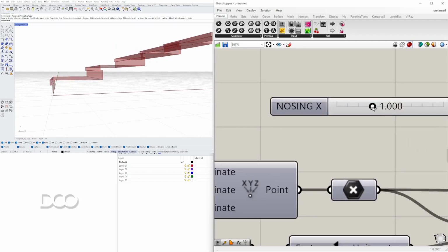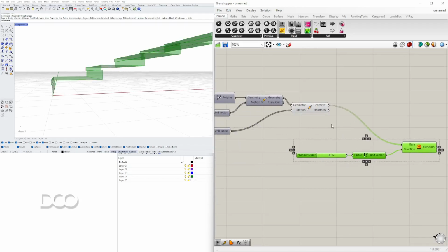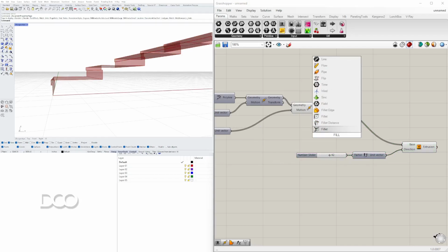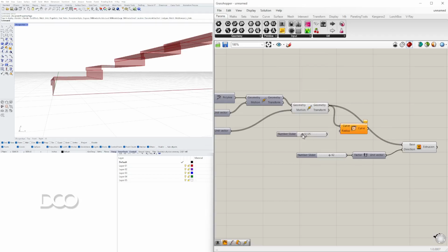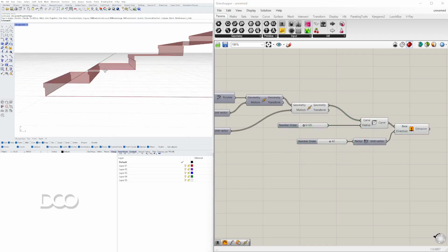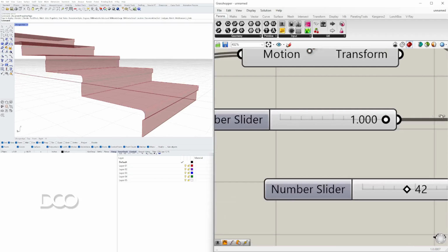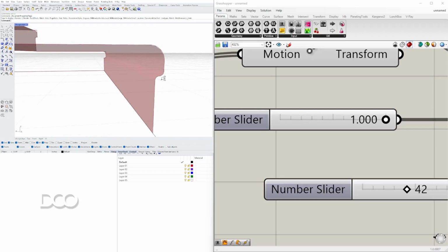And here, if we don't like the way that looks and you want it to have a rounded edge, we can fillet edge here using 0.125, which is a 1/4 inch, and then use this right, like it'll do the maximum until it can't do more, and then it'll continue on the ones where it can.